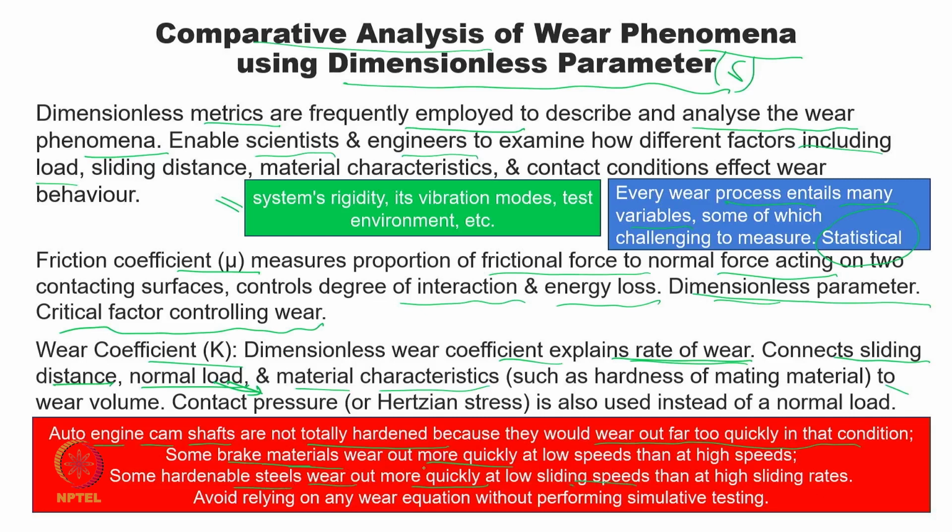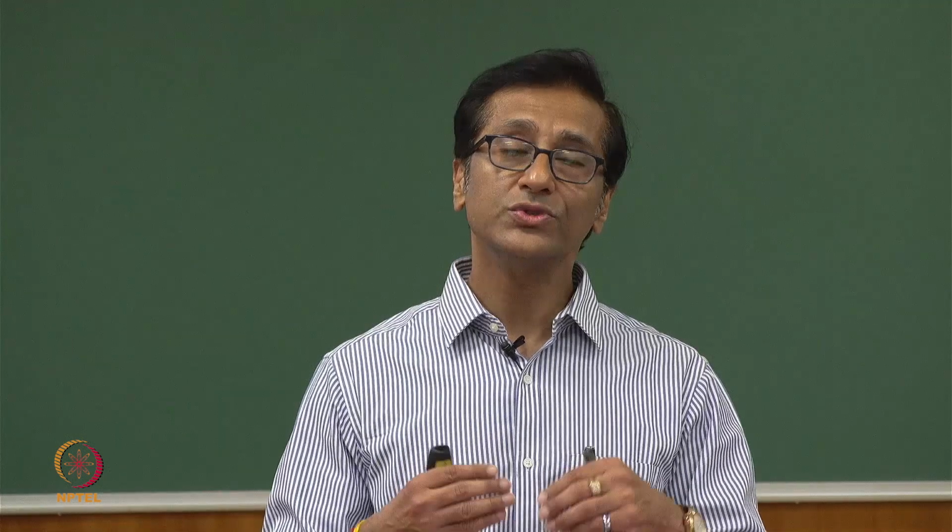this is what we mentioned already here. And then another one is that if you are really thinking about wear, do not rely only on literature. We need to do some sort of simulative testing. What is the meaning of simulative testing? I require some real experiment on the ball bearing, and there is a load, there is a rotational speed, and I want to perform a small experiment only on one ball and a race, not a multi ball roll, and maybe without the presence of lubricant, then I need to do simulation.